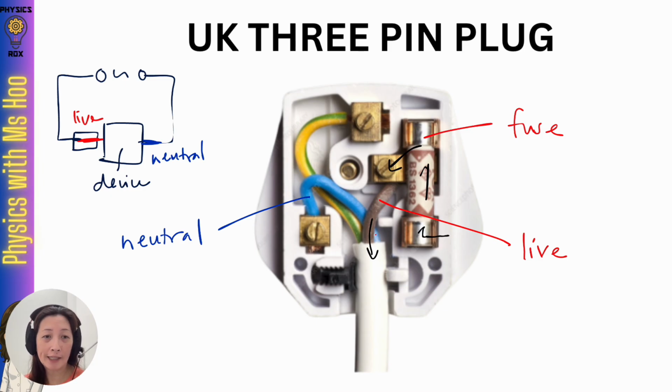So you have to remember that alternating current does change direction. So there's no fixed positive and negative terminal. Current would flow one way and then the other way. But there's always a first initial current flow coming from the power source. So if we were to do a quick sketch to help us visualize this, if this was to represent the alternating current power supply that will be provided to our households, the first flow, that means the first half cycle here, that would be where current is first flowing in to the device through the live wire. The neutral wire allows the current to be completed. And during the second half of the cycle, the current would then flow the other way, that means through the neutral and then through the live.